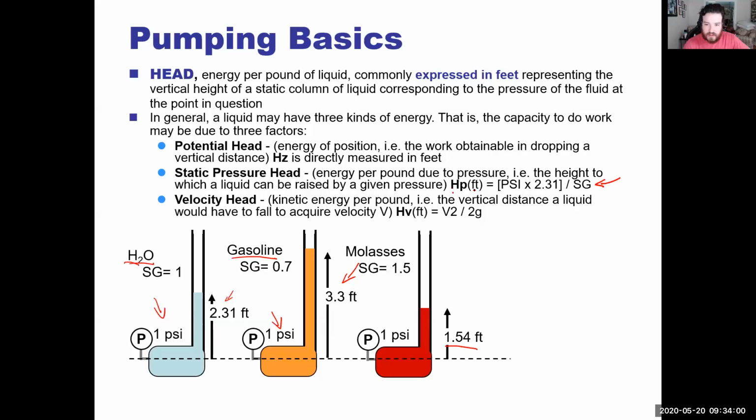All right. So you have their head in feet. It's psi times 2.31 over their specific gravity, and that's all based off of water.